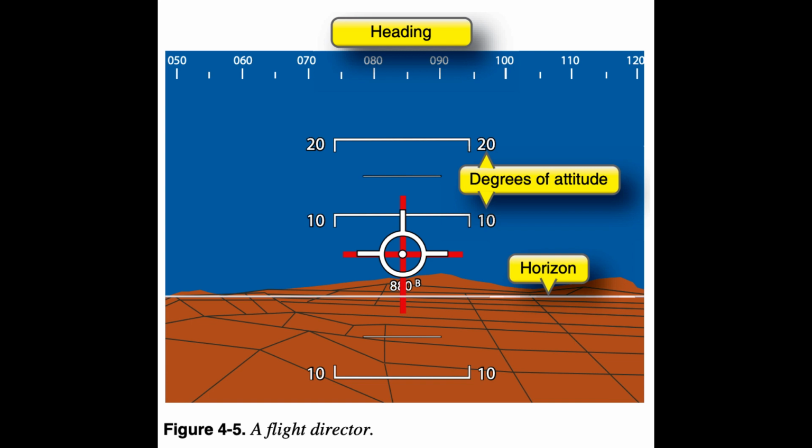To use the flight director command bars, which are usually shaped as inverted chevrons or V-shaped symbols, the pilot simply flies to the bars. Some older models use crossed bars, leading the pilot to the selected point. In both types, you simply keep the aircraft symbol on the attitude indicator aligned with the command bars, or allow the autopilot to make the actual control movements to fly the selected track and altitude.